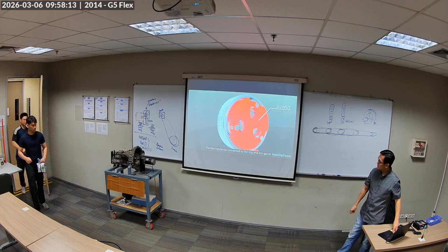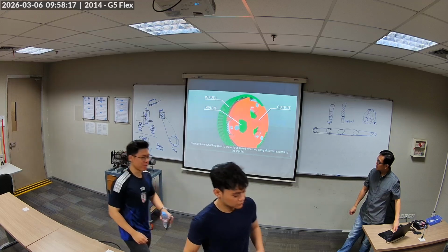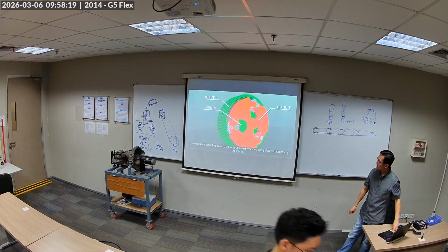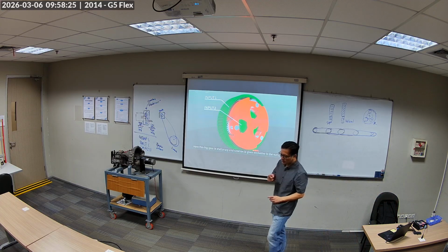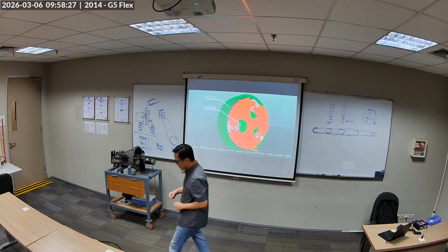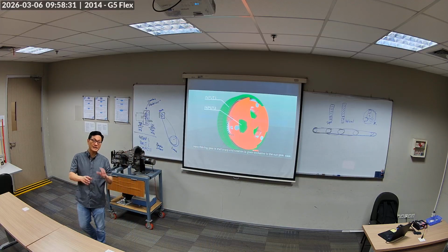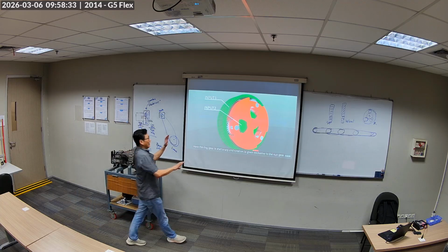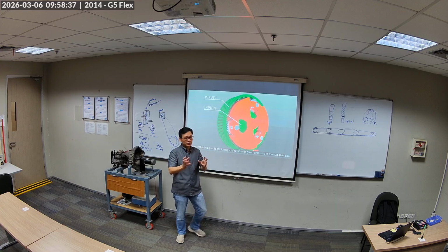The two inputs are connected to the ring and sun gears. Now, let's see what happens to the output speed when we apply different speeds to the inputs. Now it says 2 inputs, 1 output, but in many applications, one input is the one you fix. So if you fix input 2 or fix input 1, they have different ratios.